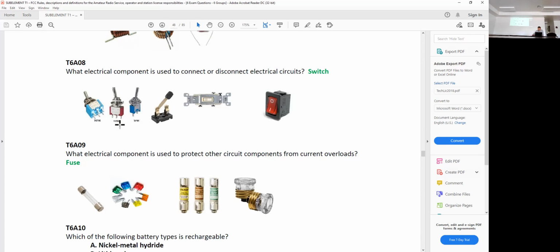And then you've got a single pole double throw with 3 wires, and essentially what that is, you've got 2 wires and one in the center, and the switch can either be connecting these 2 or connecting these 2, if that makes sense. So it's only one mechanical switch, but it's got half of another one right next to it, and you can have it on this side or on this side.